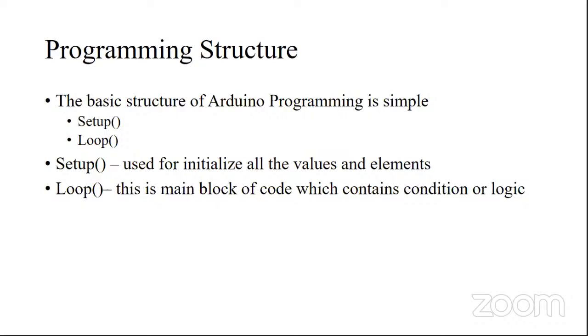We can't directly give 120 volt or something to our controller. Your digital circuitry won't handle those things. So giving more than 3.3 volt is not advisable to any kind of microcontroller. That's the reason. Okay. If I give more than 5 volt or less than 5 volt, we do have a resistor and a voltage regulator as well, but still the voltage regulator is not sufficient to control the higher voltages. So that's the reason we give only 3.3 volt to our Arduino. That's the reason, nothing else.